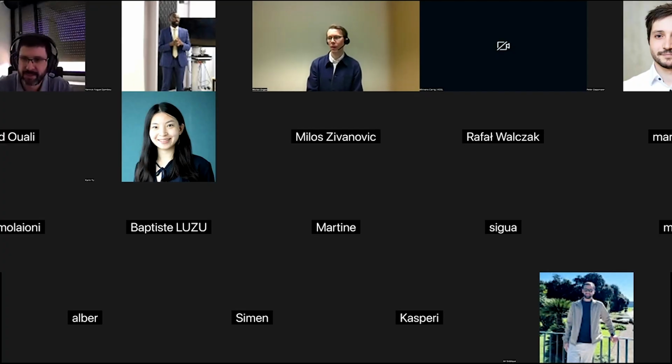Yeah. For the moment, we are not developing much related to the current Eurocode 2, but we're always happy to accept new contributions. So I can briefly mention from the top of my head something that I know is missing. We should have had something related to time-dependent property development. So we have creep, we have shrinkage, but strength and stiffness development, so far we didn't implement that. So I would really love to accept such contributions.